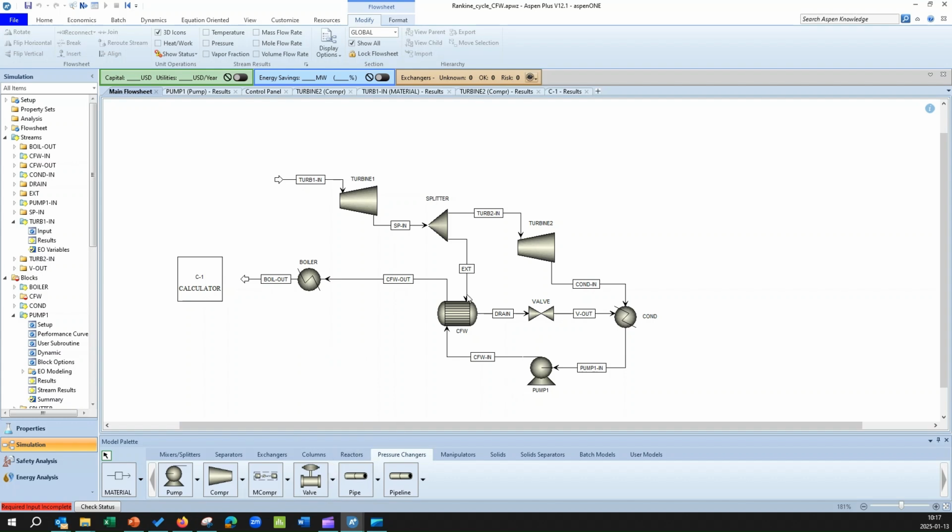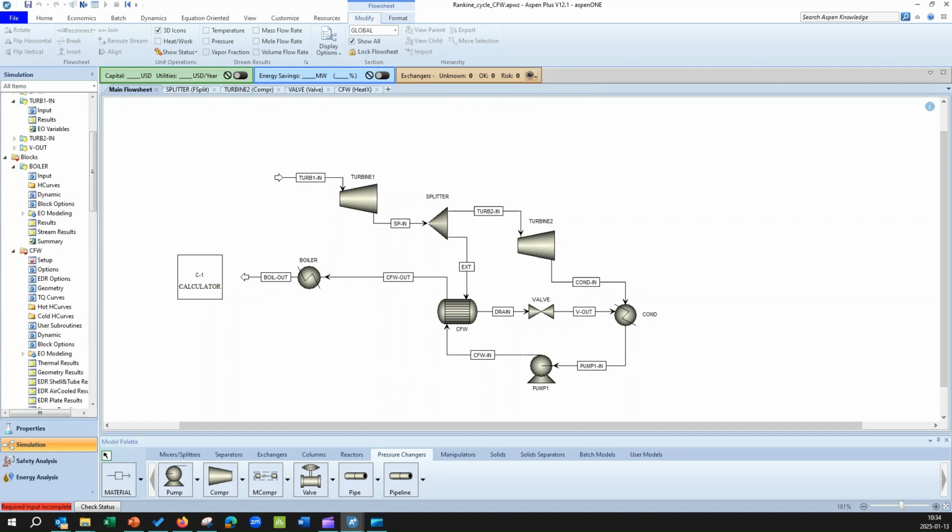And then the water that comes from the condenser is transferred to the boiler. And before the boiler, you see that feedwater enters this closed feedwater heater and the temperature hopefully rises. We will see that after the simulation. I have named all these streams properly, and now it's time to insert the information that we need for Aspen to perform the simulation.